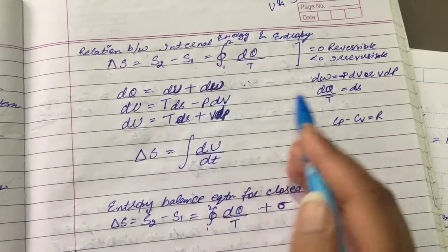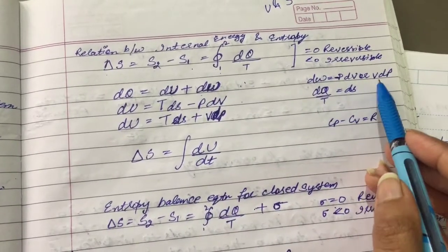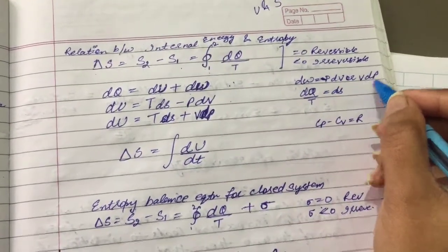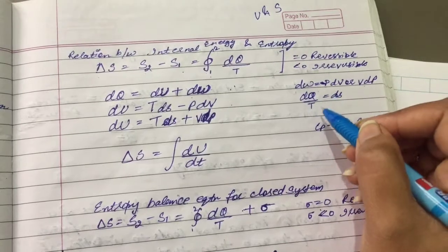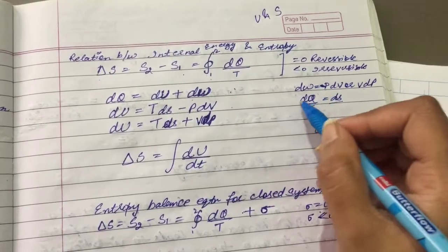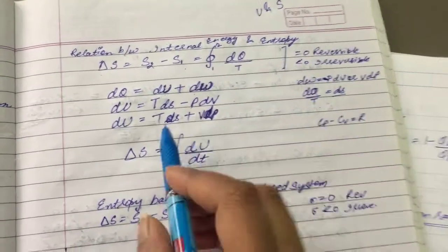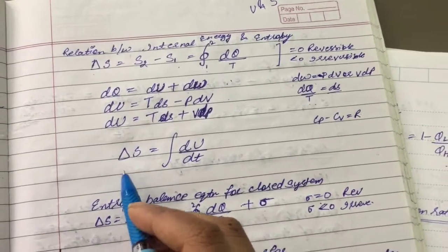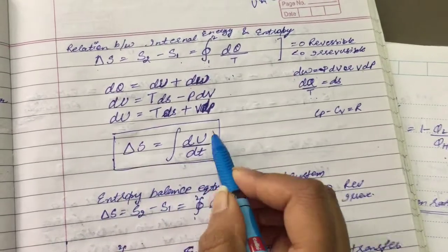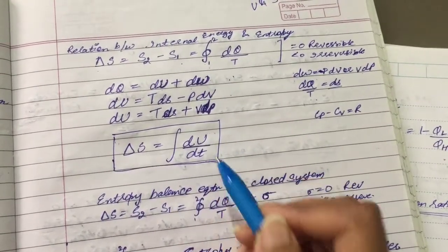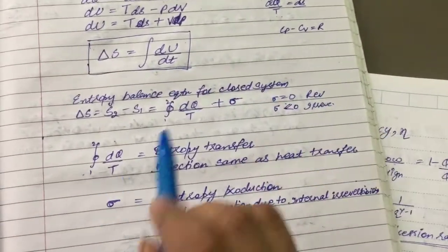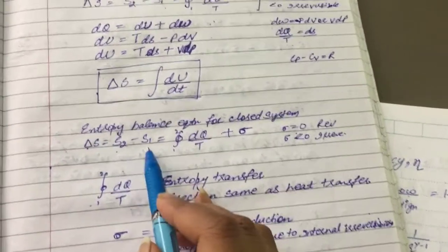For work we can write dw as minus of p dv, and dq by T is equal to ds. So from there for dq we can put dq is equal to T ds. So from here we get our change in entropy is equal to the integration of du by T, internal energy. The entropy balance equation for a closed system would be delta S, S2 minus S1,